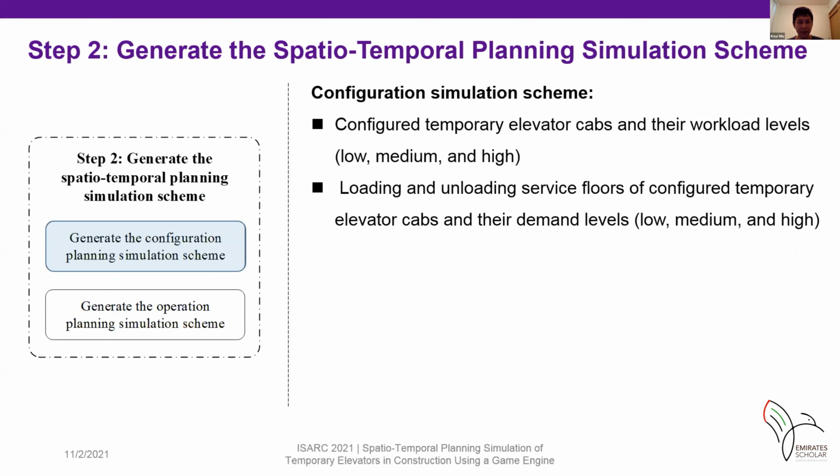Based on the imported data, the spatial-temporal planning simulation scheme is generated, which is divided into 2 parts. The first part is the configuration simulation scheme. Temporary elevator cabs, loading and unloading service floors, as well as their workload and demand levels are especially involved. The workload level is determined by the total transportation time of a specific cab, and the demand level of floors depends on the quantity of resources loaded or unloaded.